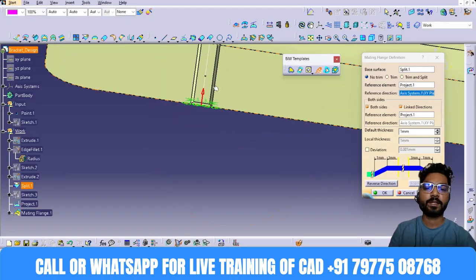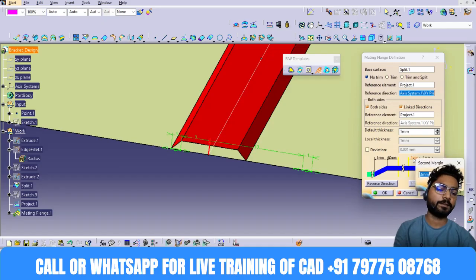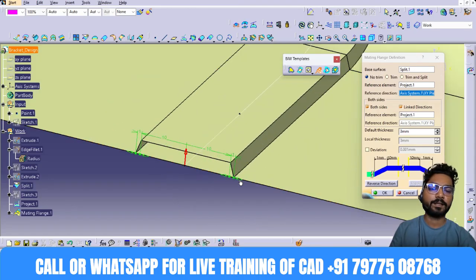Now here you can manipulate the dimensions. Let's suppose this I'll make 10 mm, this I'll make 10 mm, and the height of this I'll keep 3 mm. So you can see the flange is generated properly, right? And then I want to increase the draft.